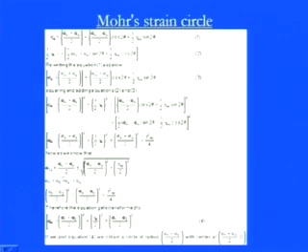If you square those terms, you will find the new terms, epsilon 1 comma 2, which is nothing but (epsilon x plus epsilon y)/2 plus minus the square root of these things. What I did here is simply make the square terms of this and put them here. So, we have the two new principal strain terms. Epsilon 1 is nothing but (epsilon x plus epsilon y)/2 plus the square root of ((epsilon x minus epsilon y)/2) whole square plus (gamma xy by 2) whole square.